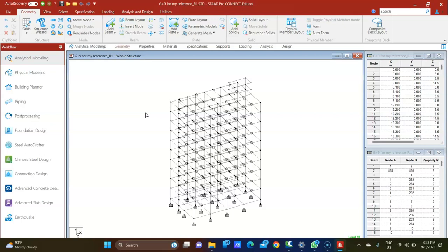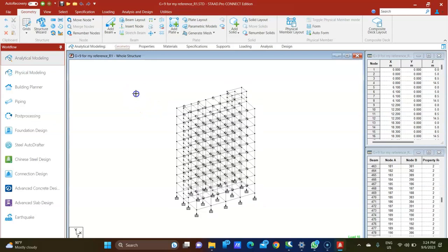But again, your structure is going to be uneconomical. If you use more steel, nowadays the steel rate is high compared to concrete. Fine? Always, if you balance the reinforcement and concrete at 2% or slightly more than 2%, it will be the ideal structural design. So people will come to you. So please see my case. Now you go for the design.